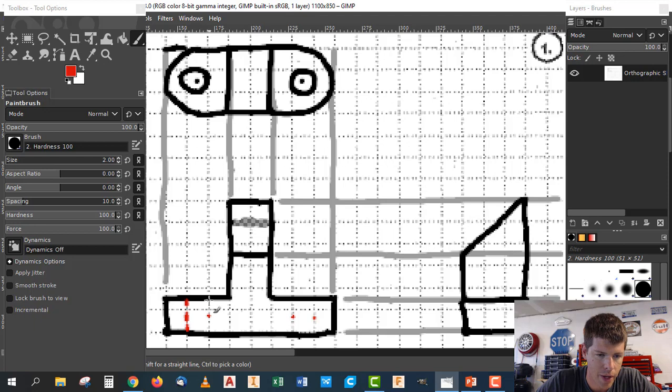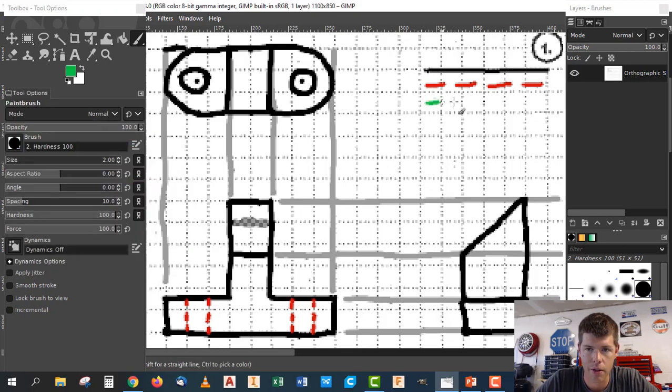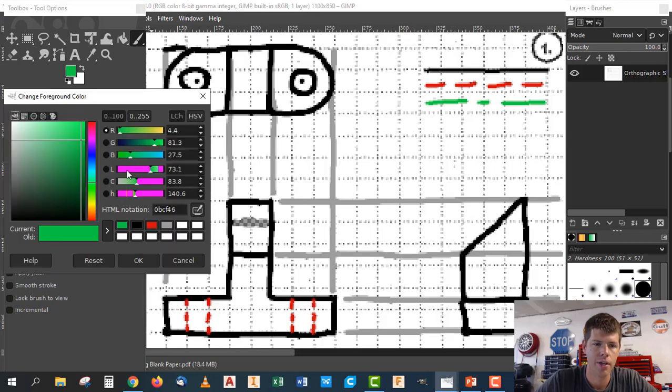Okay, so remember our alphabet of lines. And I'll draw these out in just a second again, but these are dashed lines. Really hard to do on these tiny little sheets, so do the best you can. But our hidden lines look like this. A bunch of equally spaced dashes. Our visible lines should look like this. Just a solid line. And then our center lines that we're going to do last should be long, short, long. Okay, and that pattern repeats. But that's our alphabet of lines, okay? Visible, hidden, and center.